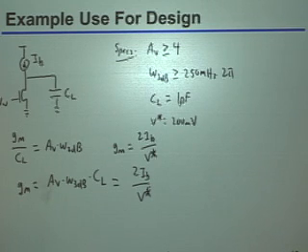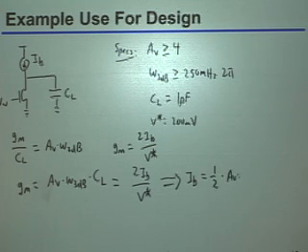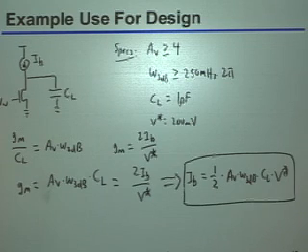Now notice, once I've done this, at least to zero order in terms of the original problem, the amplifier is almost completely specified, with one small exception that we'll fix in a second. Because I can now say that the bias current has to be equal to 1/2 times the gain times the bandwidth times the load capacitance times V star.